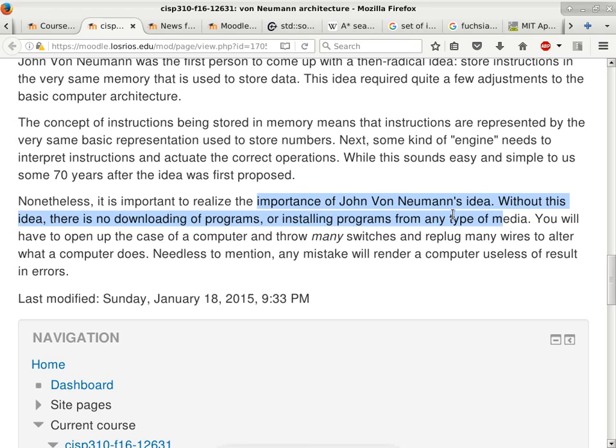And the machines to do the OTP are very specialized, because it takes a higher voltage to do the programming. So that's the good old days, and obviously it's not very cost effective, because one chip can only be used once. When you say, okay, this is not the program that I want on this chip anymore, then you have to toss the chip away, get a different one, reprogram it, and put it onto whatever circuit board needs that chip.